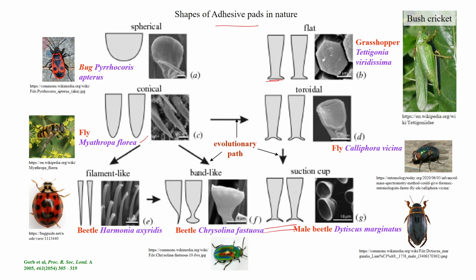Now, adhesion and non-adhesion, as far as contact mechanics is concerned, differ in the direction the force is applied. In the case of indentation, we apply a compressive load on the elastic half space, and in the case of adhesion studies, we apply a pulling load. We will soon examine, for some of these geometries, what the pulling load should be when a surface is in contact with the adhesive pad, and what force will be required to overcome the adhesion strength at the interface. So, we will come to that.